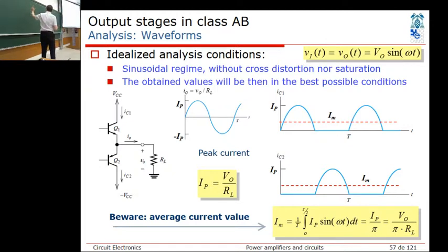Okay, so load current is simply following the sinusoid. So that peak current is actually simply the peak voltage divided by RL. Yeah, nothing fancy about that one. It's a simple Ohm's law. Okay, and this is sinusoid. On the next page, we'll see how to calculate that one, but you should know if you have a sinusoid, you should now know how to calculate the power. Okay, on resistive load. The second one about the transistor Q1.